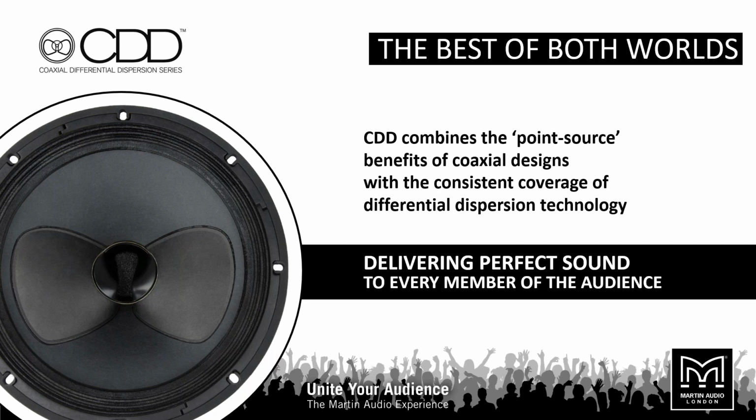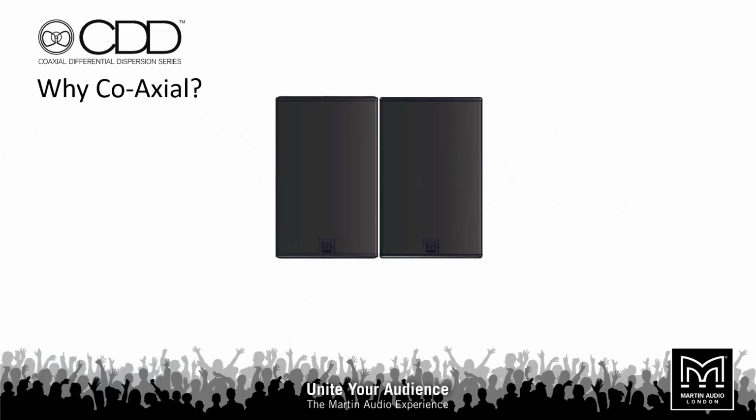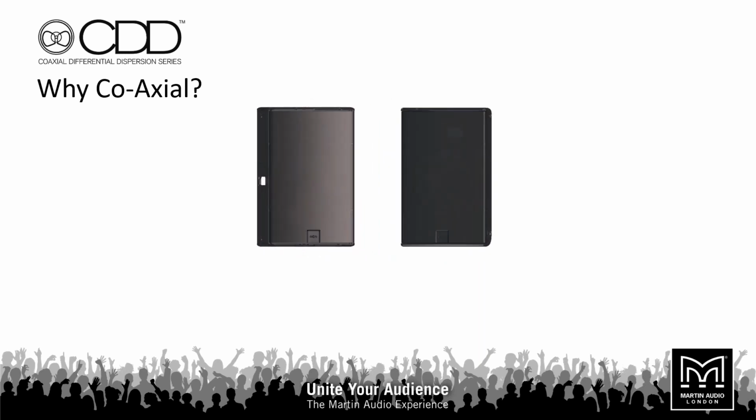So there are several reasons why you might want to use a coax over a biaxial loudspeaker. The first of which is arrival times or difference in phase position between the HF and the LF units. So if we look at this as a conventional loudspeaker on the left here with an XY dispersion, but more importantly, there is a crossover point between the LF and the HF, and the frequencies in that crossover band originate from both the LF and the HF at the same time.